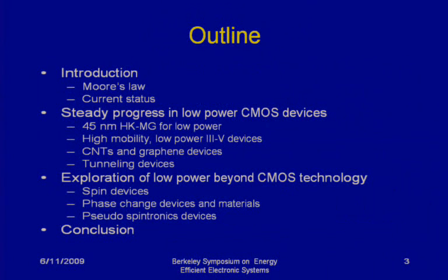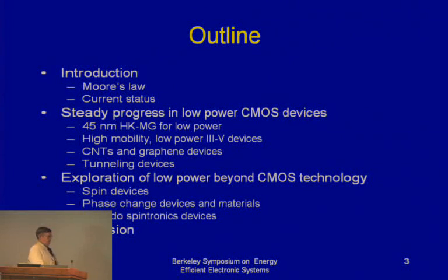So my outline today, the things I'm going to talk about, is basically divided up into two pieces. First of all, I'm going to talk about the steady progress we're making in low-power CMOS devices. This is scaling the existing paradigm. I'm then going to move on and talk about some of the exploration of low-power beyond CMOS technologies, particularly spin devices, phase change devices, and something really different called pseudo-spintronics.